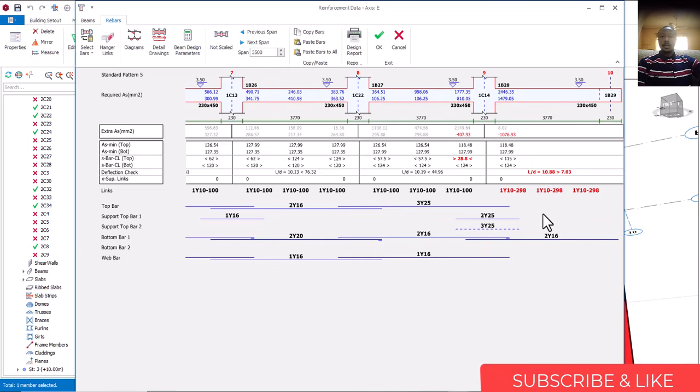So how do I now make this one pass? If you look at it, it's failing in deflection, and also the area of steel here is negative. It's expected that this place must not show red, and no value here should be less than 100. Those are the things you need to look out for. In this place, all through, no value should be less than 100, and no value should show red. And also in this place, no value should show red, and the difference should be at least around 5.